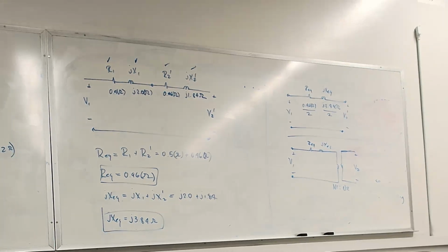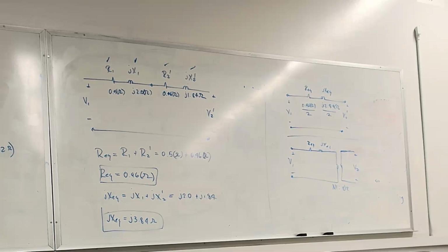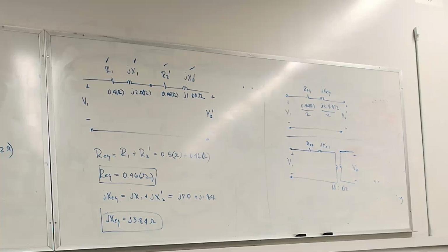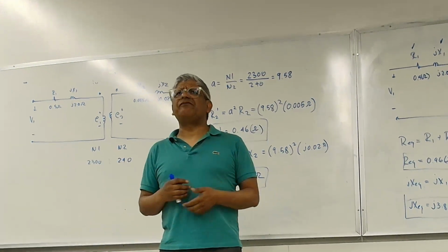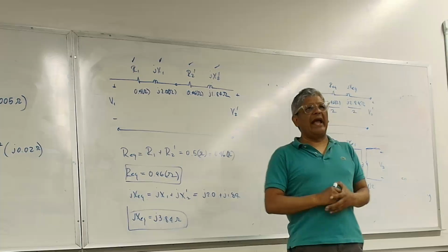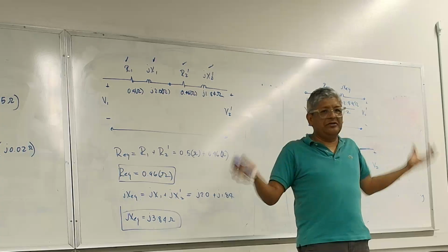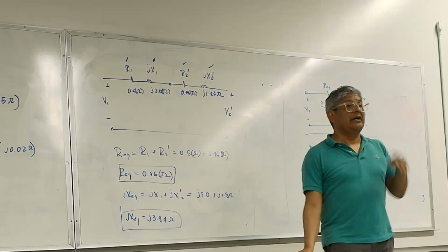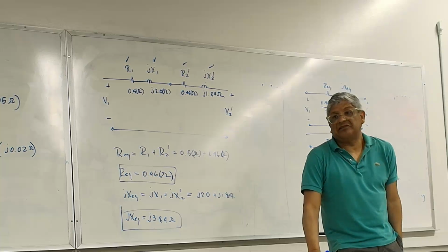That's how they maintain it, just by replacing them. There's no way you can get them to do that when you're talking about very large power transformers inside the substation. That's a whole different deal. There's a maintenance cycle that utilities have. It used to be 5 years, but just recently somebody said, no, we're doing 10 years now. Meaning every 10 years, there's a crew that's all they do. They will come and say, all right, let's go look at this transformer at this substation and make sure they're still good.